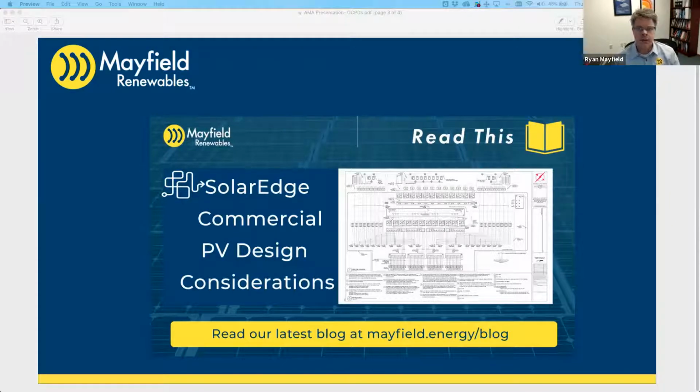And what 705.11 does, it points us over to 705.30. Well, the overcurrent protection is in 705.11c, which references 705.30. And in short, 705.30 says you have to have overcurrent protection for all your power sources, and that the rating of the overcurrent protection has to be 125% of your maximum continuous current.